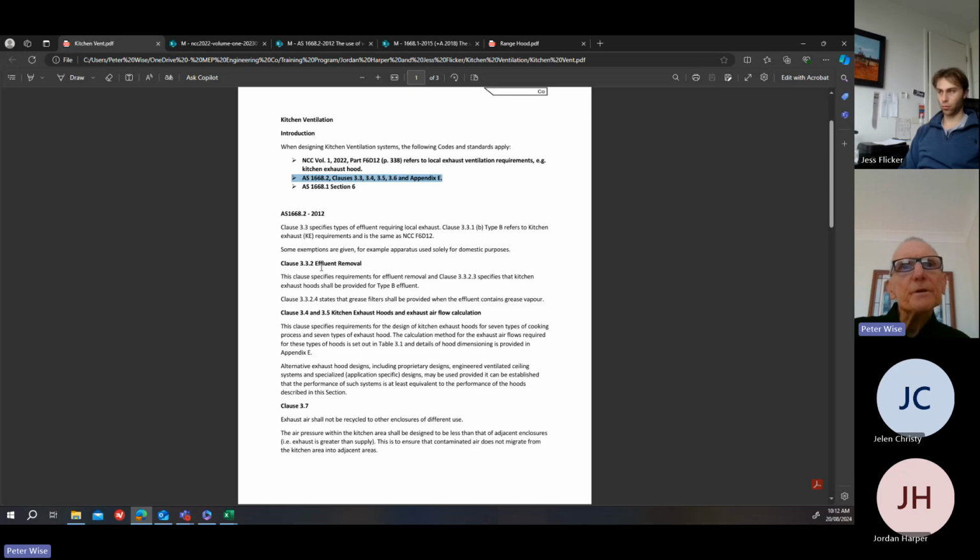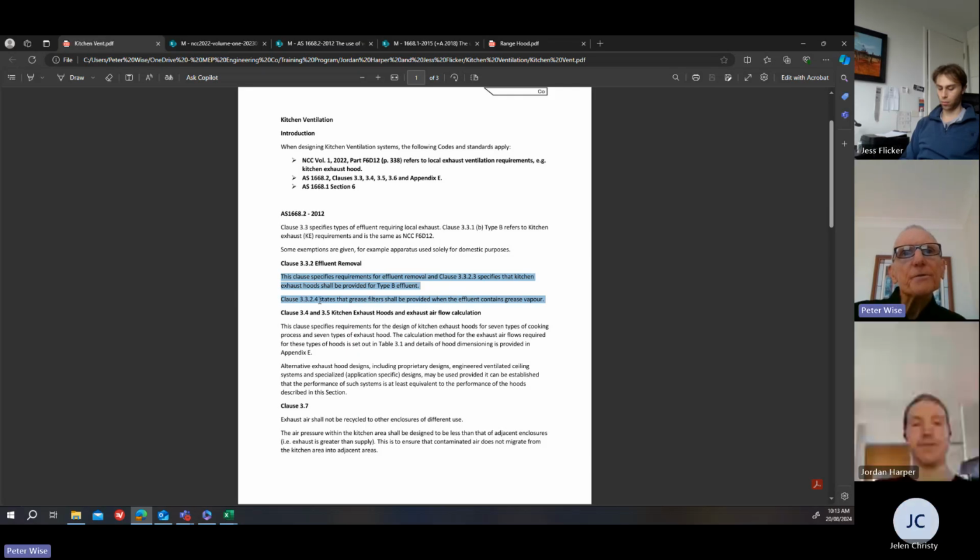Now, clause 3.3.2 of AS 1668 Part 2 specifies requirements for effluent removal, and 3.3.2.3 specifies that kitchen exhaust hoods shall be provided for type B effluent. 3.3.2.4 states that grease filters shall be provided when the effluent contains grease vapour.